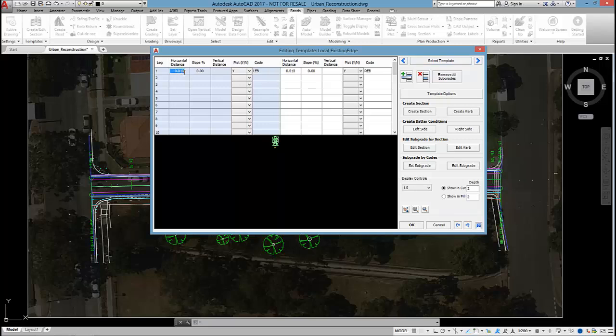code, just a little bit offset either side, 10mm. And what I'm going to do is create the edge strings here as road objects. And if those road objects get created with this particular template, so an LEB and an REB exists, I can use the software's AutoCAD return command and transition my design back into the existing edge.